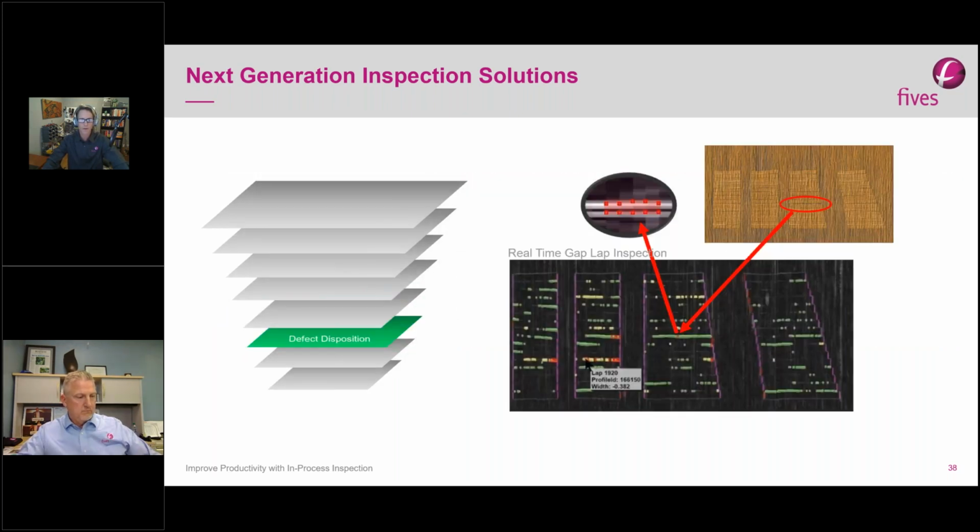Next slide. The last processing step is to determine if the measured feature meets the threshold to indicate whether it's a defect. Gaps and laps have different regional criteria: gaps within a course, gaps between courses, gaps in every region. You need a kind of lookup table to make sure you're applying the right specification.